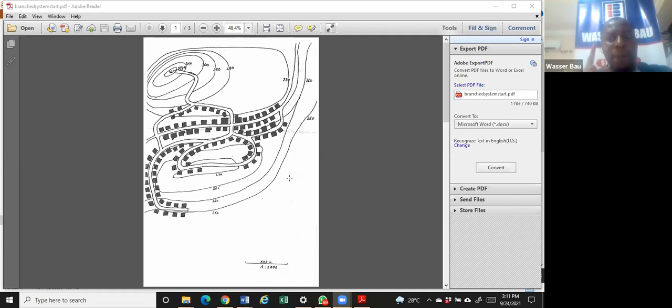And that map will not just be an area map, it must be a map that has information. And that information must be topographical information or elevation information, what we call spot heights. Or you could say it must have contours. Why is this necessary? Because remember, 90% of water reticulation systems are by gravity.